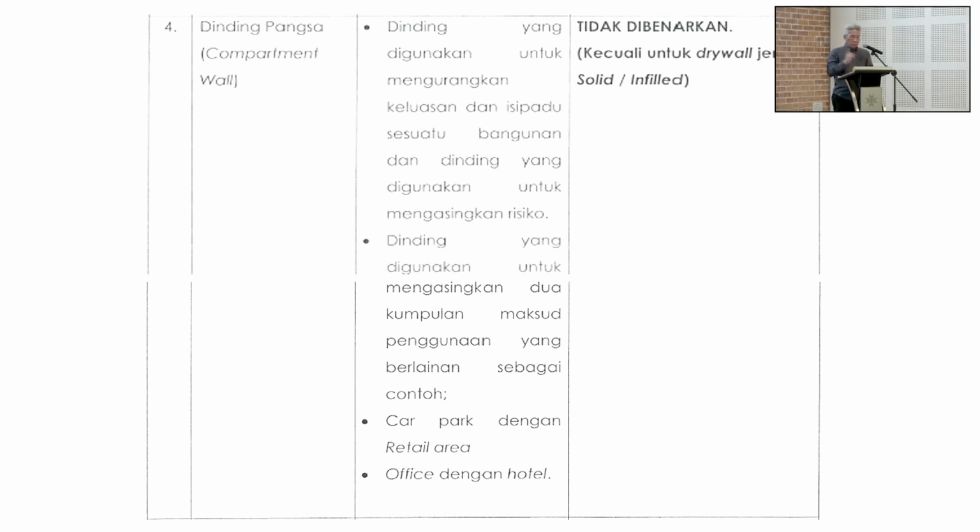But for compartment walls, they also recognize that, but they say, okay, let's have some leeway because compartment walls are not party walls. They are not separating walls per se. They are really compartment walls within your own arrangement, and you're using it for purposes of, say like a large warehouse, where you may need to vary your tenancy requirements.